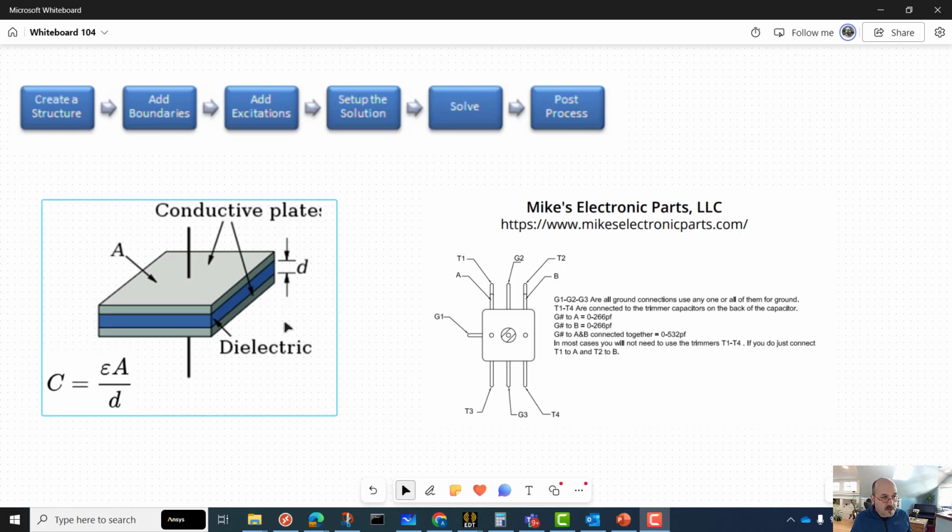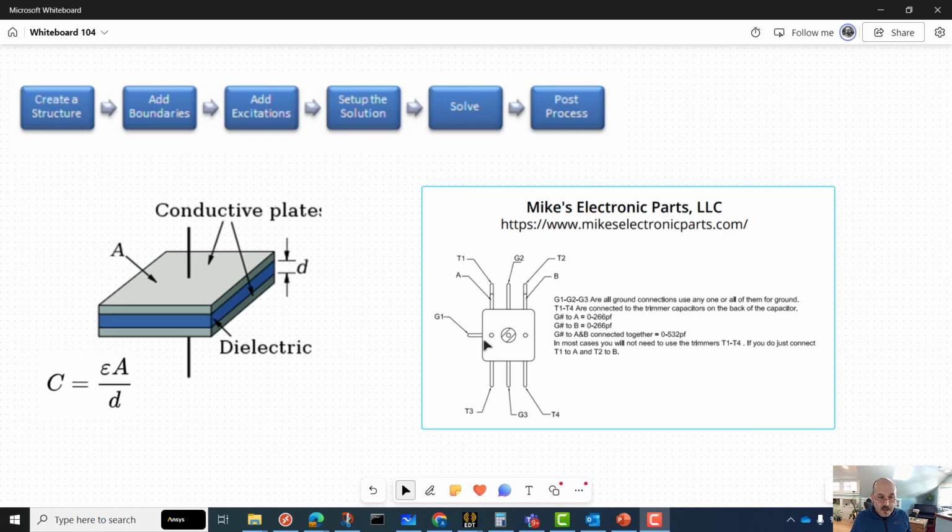What we are trying to do is build a simulation model of the actual capacitor that we use on our crystal radio. So you certainly remember this. We all had this on our radio board. There was a knob on top of it where we could turn it from left to right about 90 degrees. And in doing that, you can see the values written here. We were going from a capacitance value of 0 to 532 picofarads.